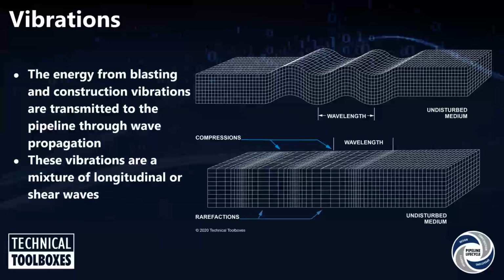And we don't have to worry too much about that. Just keep in mind that the saturated soil can pass the wave, the vibration energy, better than a soil that's not saturated. Also keep in mind that a competent soil or a solid bedrock can pass the vibration energy far better than a weak soil, right? So here is a situation where a weak soil is actually better than a strong soil, because a strong soil can pass the energy from vibration to a long distance, whereas vibration energy in a weak soil tends to attenuate fairly quickly. Next slide, please.